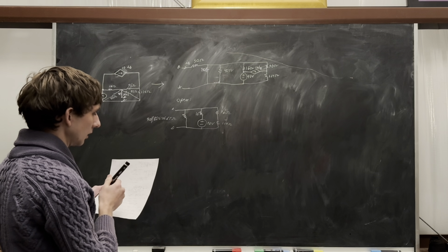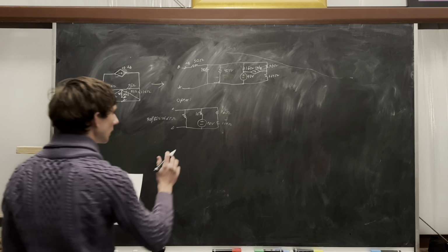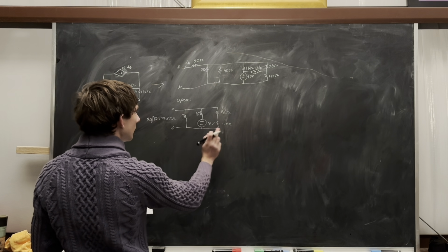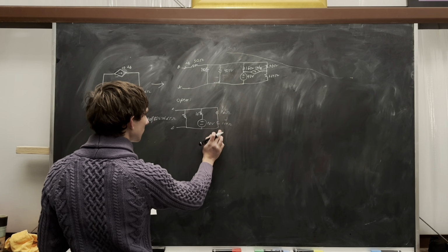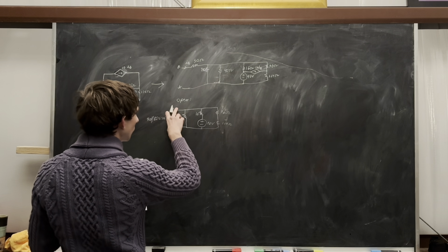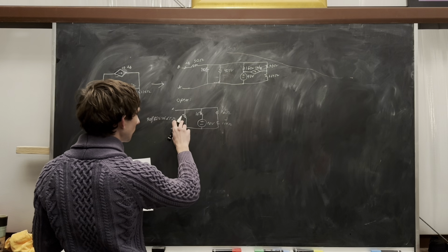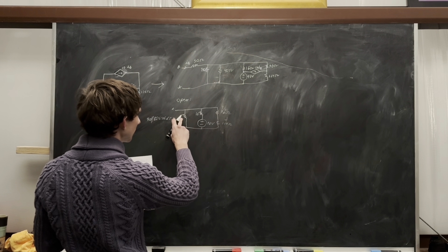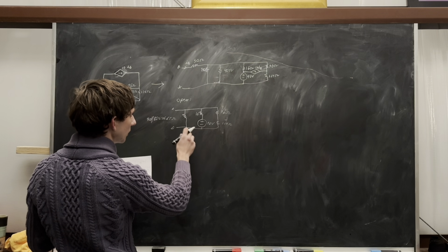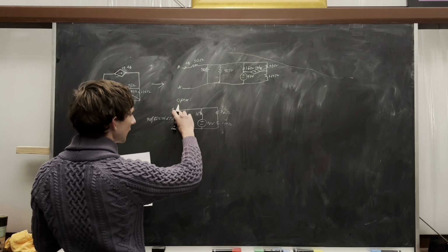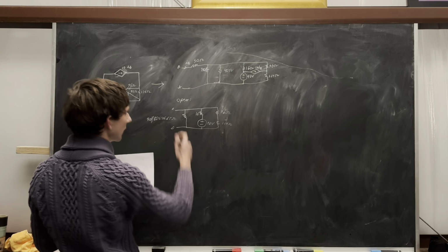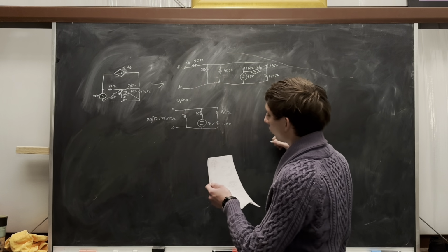For my calculations, I did a sort of voltage divider. It's kind of hard to see here, but if we move this set of two resistors over here, they're going to be in parallel with all these resistors, with just this one resistor here. And then if we combine these two with this guy, we'll just have a voltage divider between the 16 ohm resistor and whatever the value of that is. So I did that all in one step.